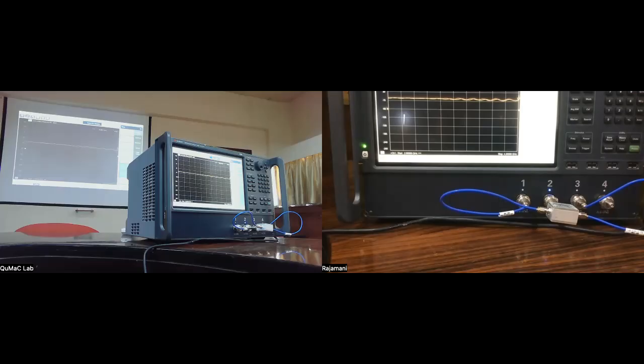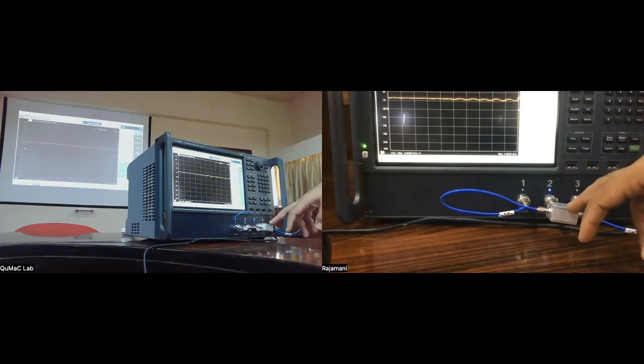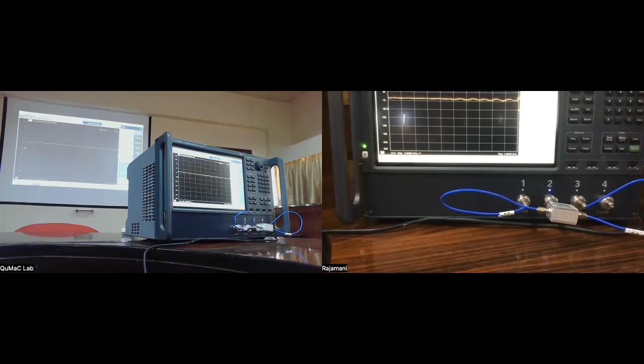You will make the resistor using some material. It will have some finite size, which means it's going to have some capacitance to ground. It might have some inductance. These things might be irrelevant at very low frequencies, but they will be relevant at high frequencies. So that's why the difference between, as I said, expensive versus cheap instrument or device, that's what they do. Like this one, which is the low cost version of a resistive splitter, probably has a material choice for the resistor where we know that material is going to be frequency dependent, versus something which is not frequency dependent. So that changes the cost.